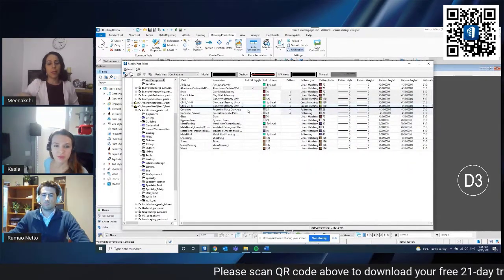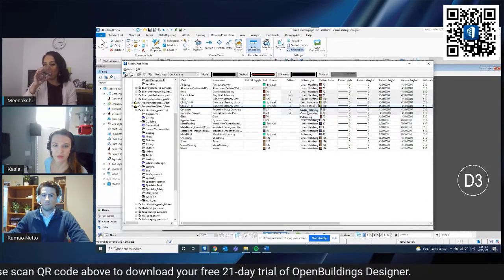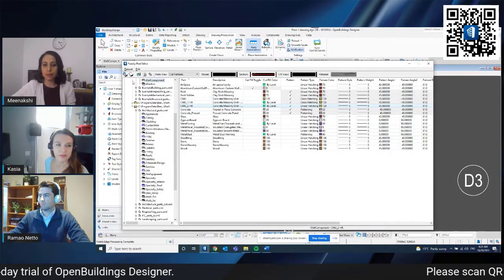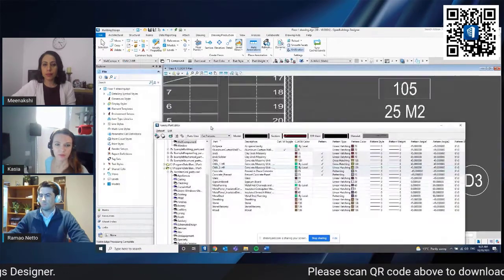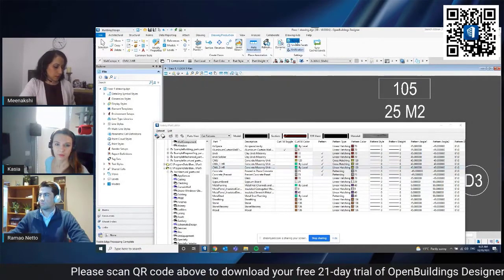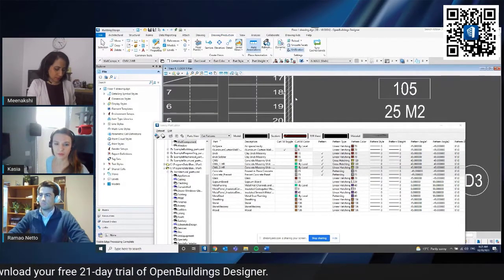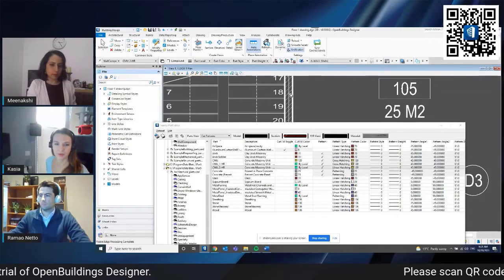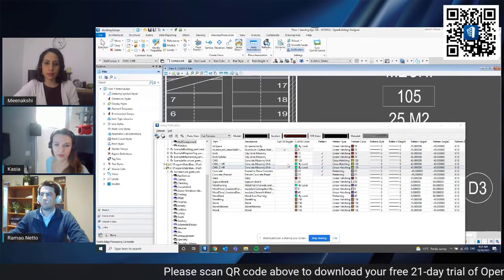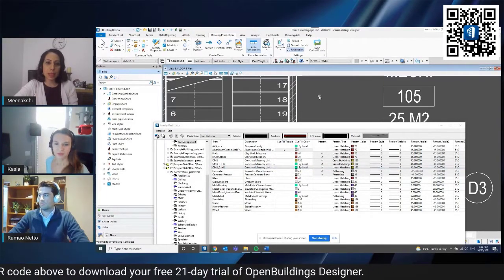So I will just maybe change one of those elements. So maybe instead of cross-hatching for a moment, I will apply patterning or maybe linear hatching. And let's just see, move it a bit. Again, I will just commit the changes and then reload the model. And I can see that the cross-hatching disappeared. We now have this line hatching. And of course, we can change it also to patterning, or we can just apply a simple fill. To do that, we just need to toggle. So it's another example how to do it.